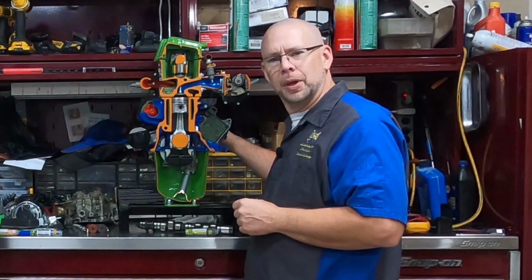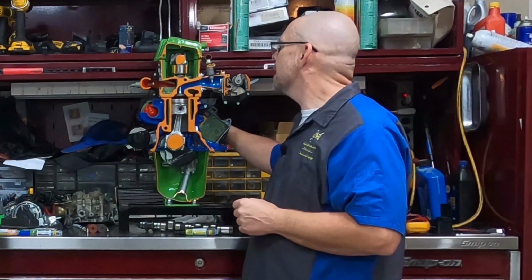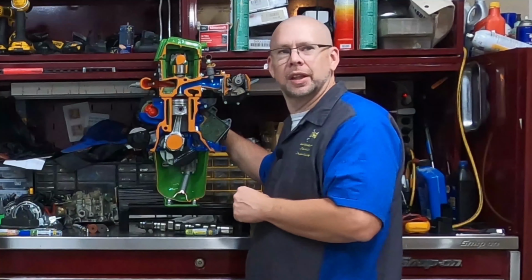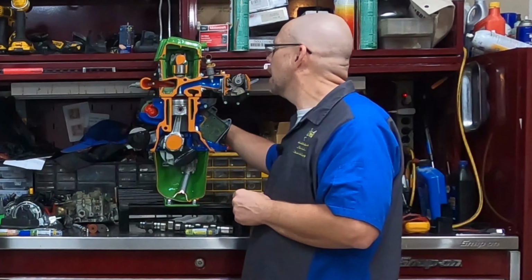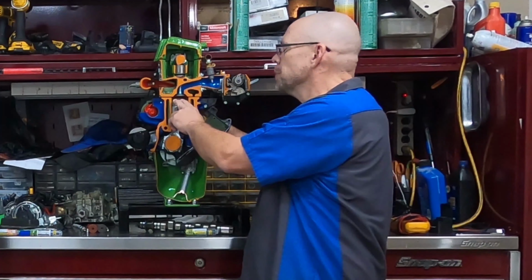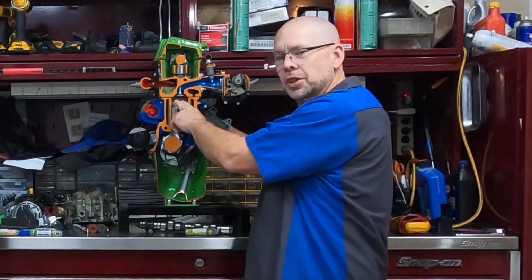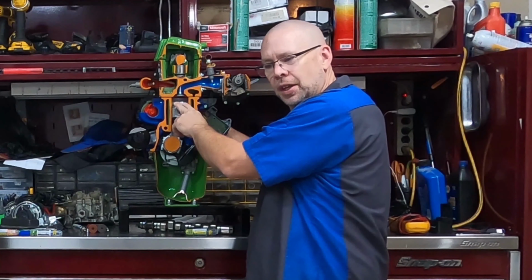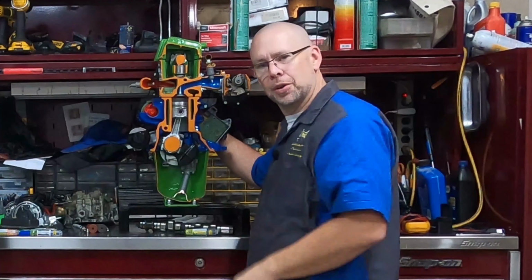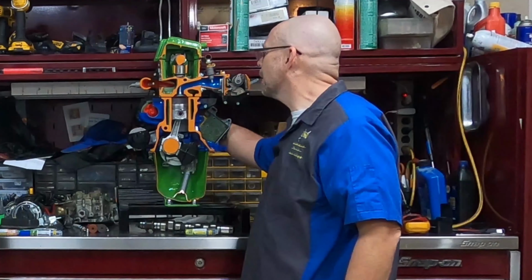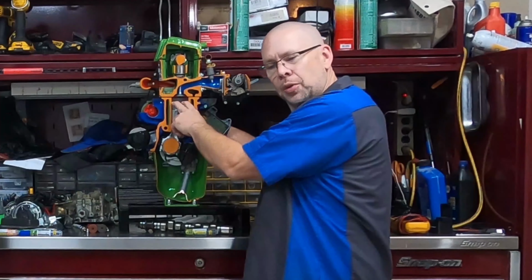We'll fire that spark plug, and then the mixture will ignite and it will start to burn. And it generally burns until we get between 10 and 20 degrees after top dead center on the way down the power stroke. At that point, the piston is moving downwards rapidly.